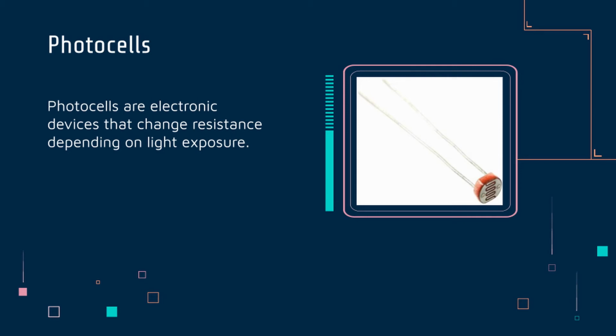Photocells are essentially resistors that vary their resistance and are sometimes called photoresistors or light-dependent resistors. They're commonly found in light sensors to detect the amount of light present. For example, automatic lights, such as street lamps, utilize them to control when to turn on. However, they are also very inaccurate, and variations can be up to 50% among groups of the same photocell. Photocells also are different from photodiodes, as they do not have a p-n junction and do not directly convert light into electricity. Instead, they alter their conductivity depending on the presence of light.